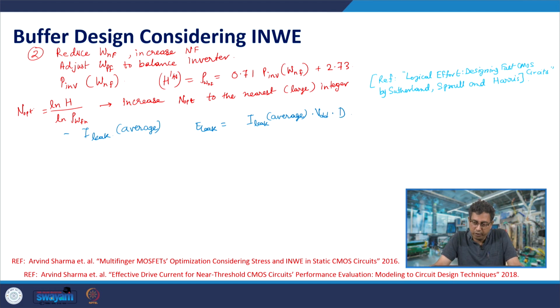The delay of the buffer gives us a fair idea, assuming it is the time for which you need to keep the circuit in an operating condition. Otherwise, you can power gate the circuit. So, the total delay of the buffer is a good measure to calculate the energy, otherwise you get leakage power.